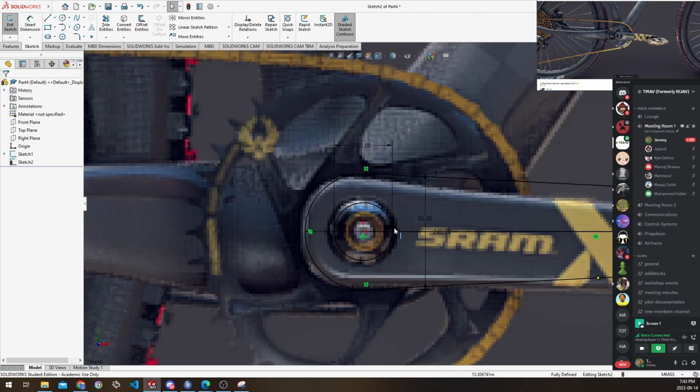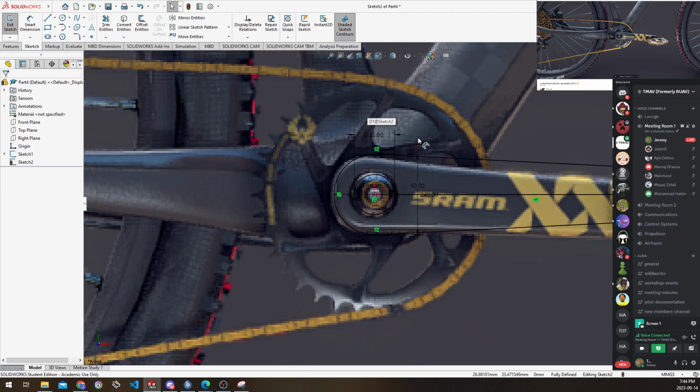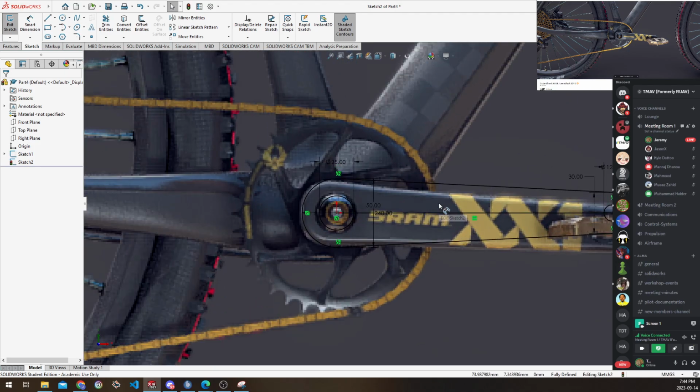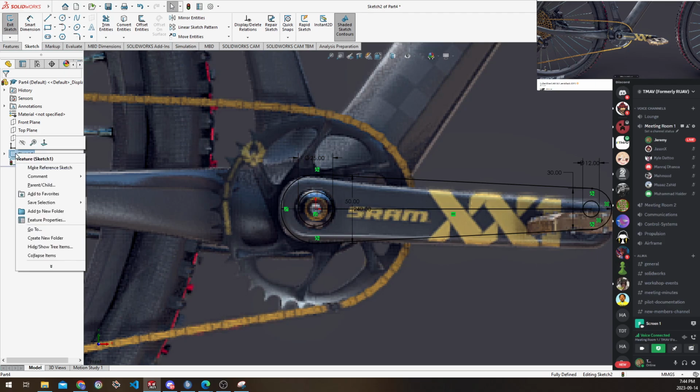And just again, keep in mind whenever you're doing CAD like this, always make your dimensions round numbers in a known format and in a known dimension, preferably in millimeters. It'll make your life and everyone else's lives around you a lot easier to deal with CAD. Fitting parts together that are standard dimensions is much easier than fitting, you know, random stuff together. So keep that in mind. It also reduces the need to measure things a million times because if you know everything is 3 millimeters, you know everything's 3 millimeters, you know?